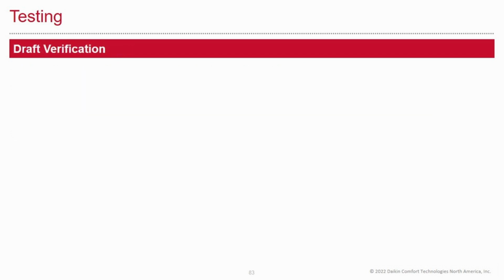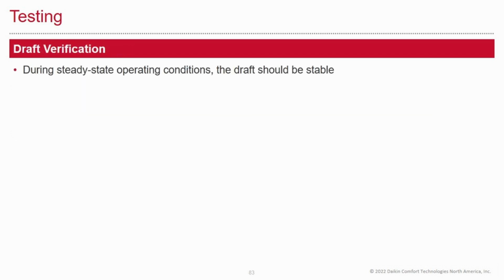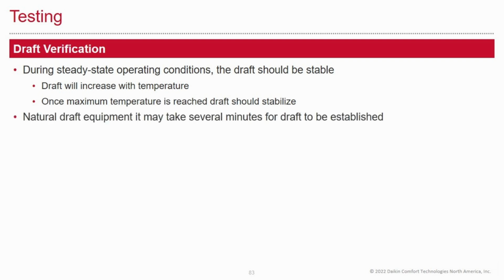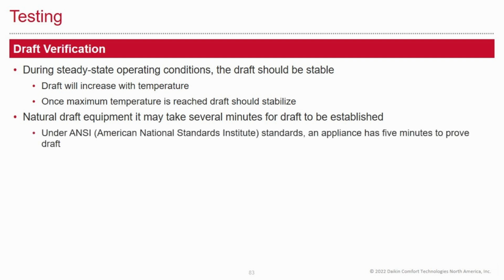Draft verification. During steady-state operating conditions, the draft should be stable. Draft will increase with temperature. Once the maximum temperature is reached, the draft should stabilize. Natural draft equipment may take several minutes for the draft to be established. Under ANSI, the American National Standards Institute, standards, an appliance has 5 minutes to prove draft.